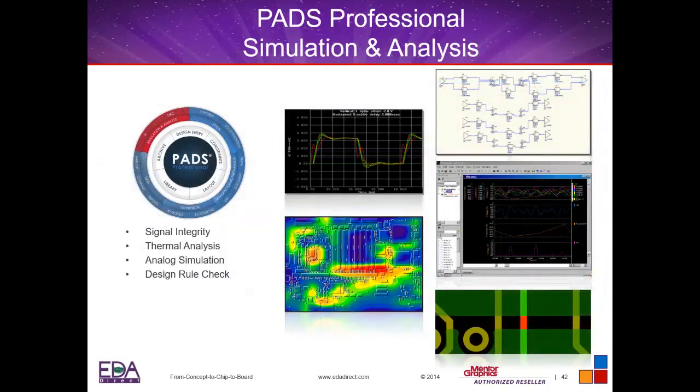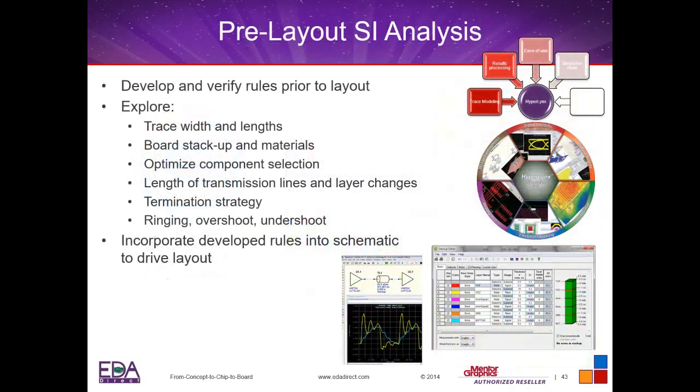And then some of the other nice features that come with the tool are the HyperLynx tools that are going to be available to you. So you're definitely going to have signal integrity, thermal analysis, analog simulation, design rule check. These will all come with the PADS Professional suite. So if you need to do any kind of pre-layout analysis in the schematic, you've got full capability to look for termination problems, ringing, or overshoot problems.